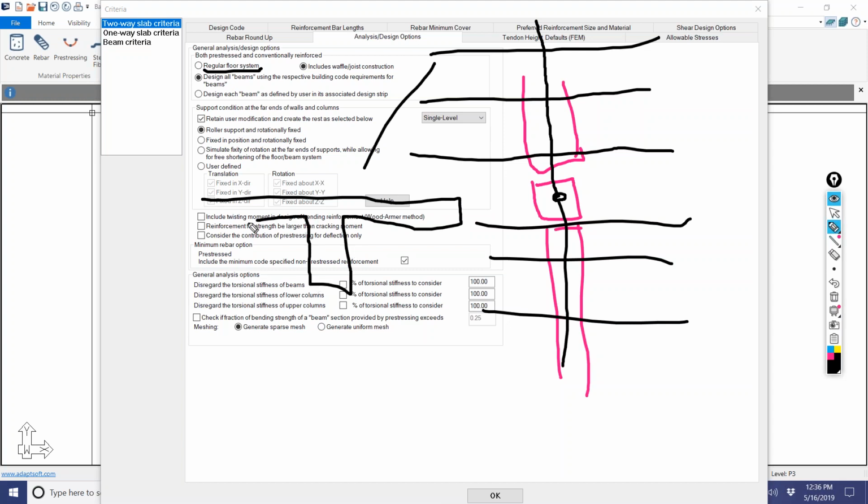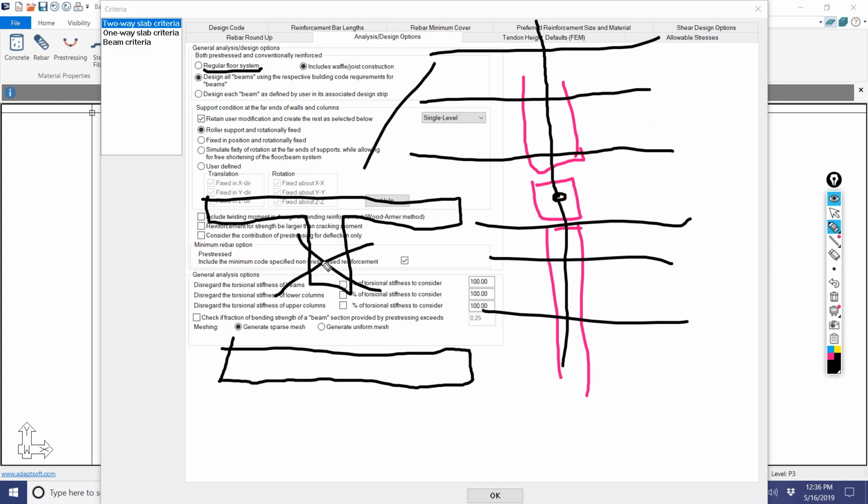It's a T-section, but analytically we assume that this is a structural or an architectural beam. It's included in the analysis. It's discretized in the frame elements, but when we analyze and design the section, we actually avoid using the beam stem. This goes away. So this is what we call the physical cut. This is called the idealized cut. And this is what we use for generating stress checks, rebar, and so on.